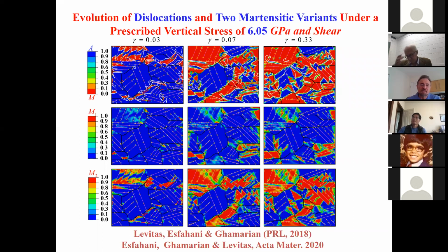it's not well proved. It's well known that martensite nucleates at dislocations, but there are not a lot of clean works which show this. Because when you prepare a sample, this should be TEM probably, the large dislocation pile-ups can relax. And I don't know of experimental confirmation of exactly this mechanism. And as I said, it may also be a different mechanism. For example, in TRIP steel, it's not a dislocation pile-up, it's the intersection of shear bands.